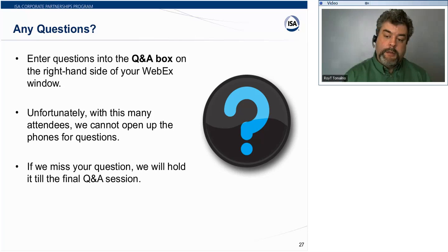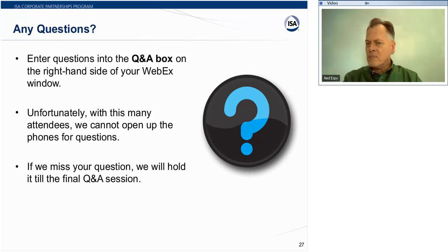All right, thanks. Another question that came in from Charles. Do you always suggest an up-down cal versus just an up calibration? I'll take that one. This is Ned. It depends on your practices, but for a differential pressure transmitter, I would recommend doing an up-down test. You mainly are wanting to check for hysteresis, or verify that the diaphragm, whether you're pushing the pressure in or going up in pressure versus when the pressure's dropping, does not retain some memory and cause a difference in the measurement, whether you're going up or down.